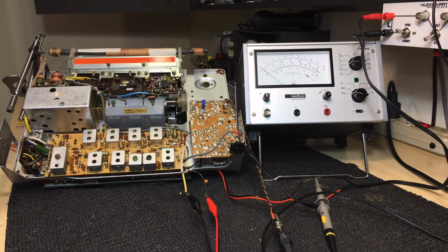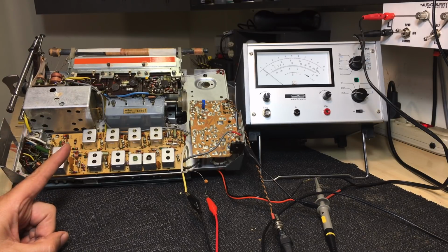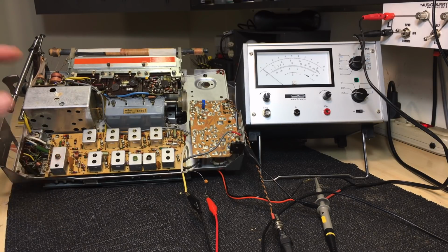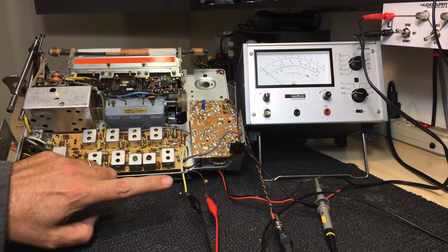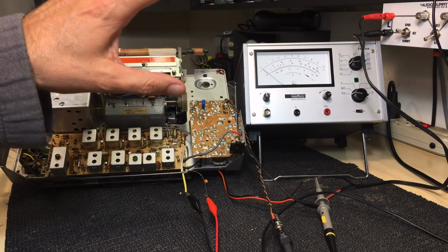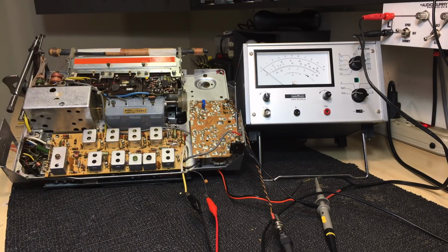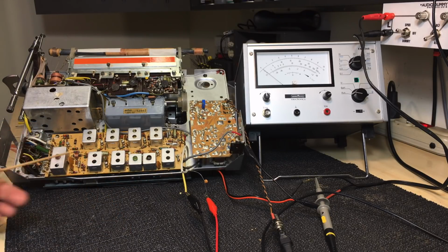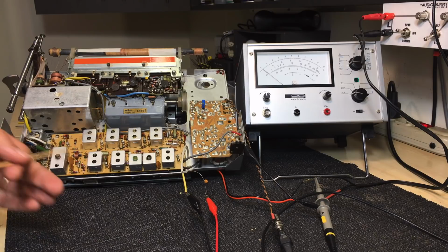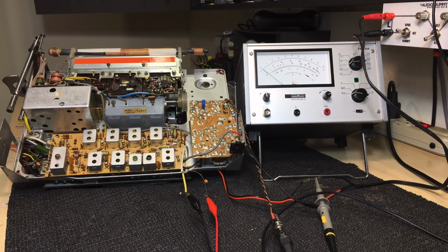The other thing they tell you to do is put this on sharp. Now you're trying to get this as sharp as possible. You put sharp selection on the front, and you put the volume on maximum so that you can feed in the smallest signal possible here and still get an audible signal and a measurable signal. The idea being that the louder it is in terms of AF amplification, the smaller the signal you can put in here and the less effect the automatic gain control or automatic volume control will have on your measurements.